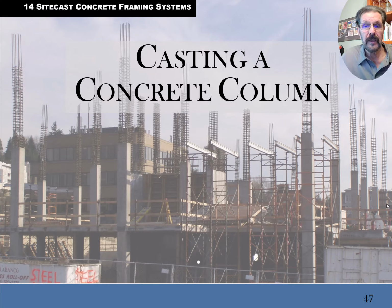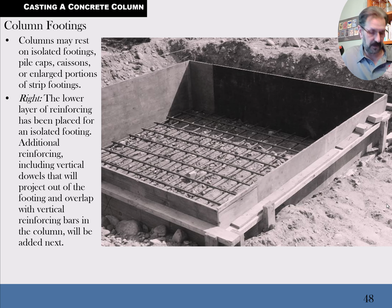Anyways, casting concrete columns. Gotta watch my time here. Concrete columns start off with a pad footing. The pad footing has the rebar mat down near the bottom. In general, we need that mat of rebar to be 3 inches off the ground so that moisture in the ground doesn't soak up through the concrete and rust the mat in the concrete. So it needs to be 3 inches off. But otherwise, if it wasn't for that, we'd want it about an inch and a half off the ground.